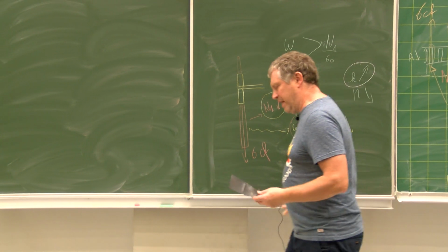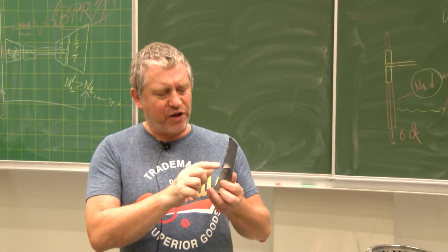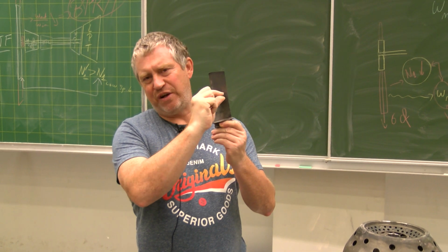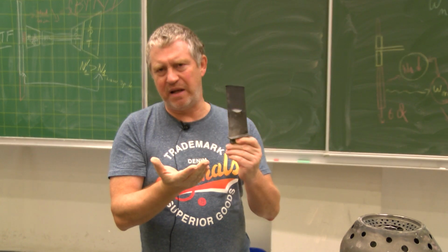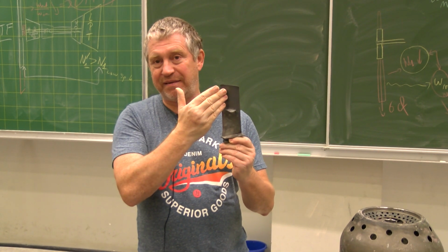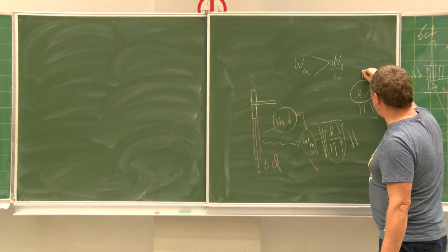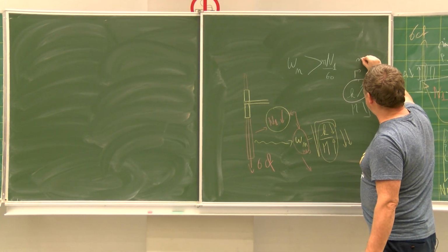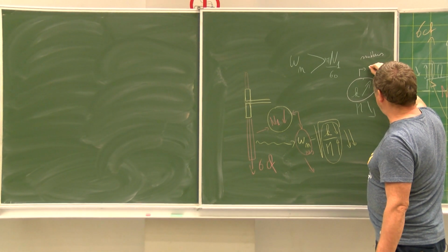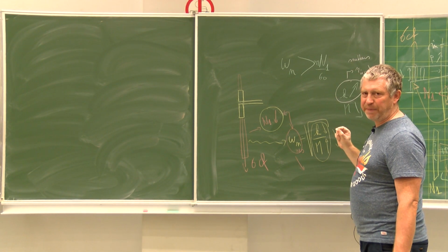Of course, this is not ideal as a solution because you are increasing, let's say, the contact surface you have between the flow, the air, because it's a compressor, and the blade. And this solution, this is called snubbers, has the trend to decrease the isentropic efficiency of the compressor.